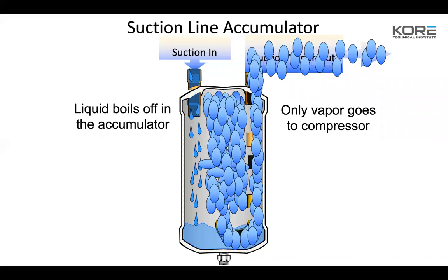So you might get an excessive frost out of the gate because that valve's wide open, you're shooting straight liquid through that valve. It's very saturated. It's boiling off at a massive rate, but it may be very saturated. So you might see excessive frost. Get that case down to the optimal temperature you need to, of what it should be, and then watch what it does. If you're still excessively frosting, you might need to go after that expansion valve and calibrate the superheat. But, as always, never make that adjustment until you're within 4 to 6 degrees of operating temperature.